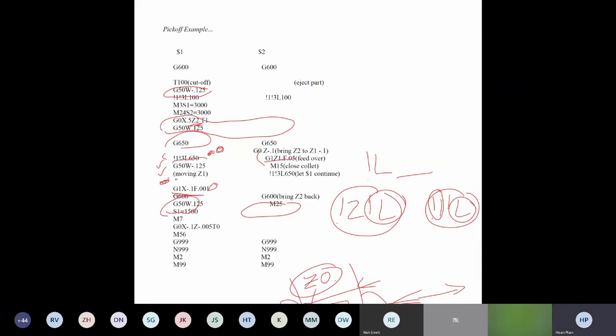So the machine right now, if you're calling tool number 1 right here, it will go in and read the geometry and offset everything for this one. So it doesn't matter if the cutoff is left-handed or right-handed, it will automatically know. For example, if it's right-handed like this, it will know this side is Z0. And if you know that you're setting up the machine, you're never going to set the longitude on the gauge tool. That means the machine automatically understands Z0 is right here.